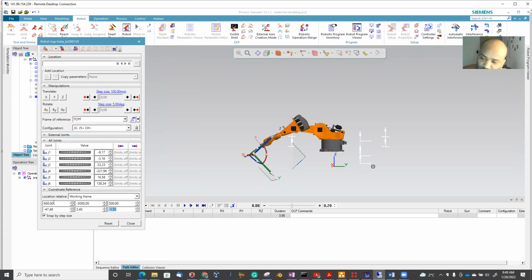There is mathematics called inverse kinematics and forward kinematics. Forward kinematics translates information from the joint space to operational space. And the other way, which we call inverse kinematics or reverse kinematics or indirect kinematics, takes the information from the operational space and translates it into joint space.